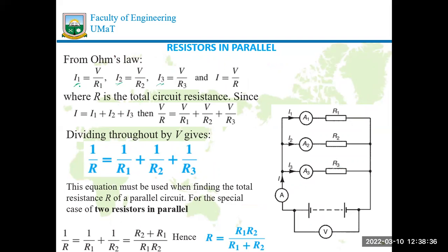Okay, the current is directly proportional to the voltage and inversely proportional to the resistance in that branch, having in mind that the temperature remains constant, provided the temperature remains constant, such that this R will not be varying based on temperature. Remember, R theta is equal to R naught times 1 plus the coefficient times the temperature difference. So we can represent the current in these forms.